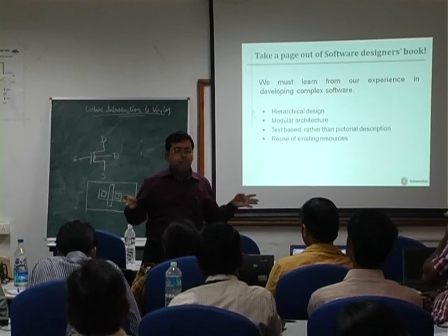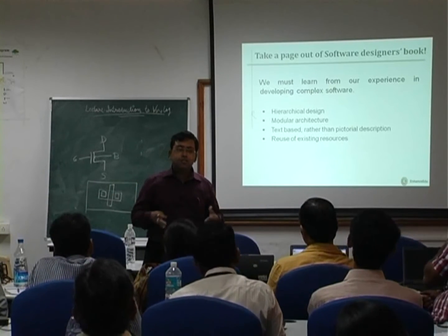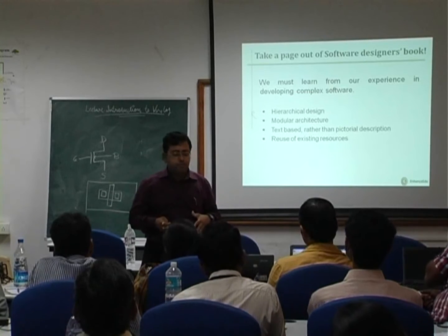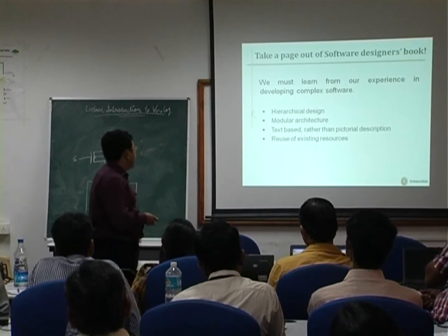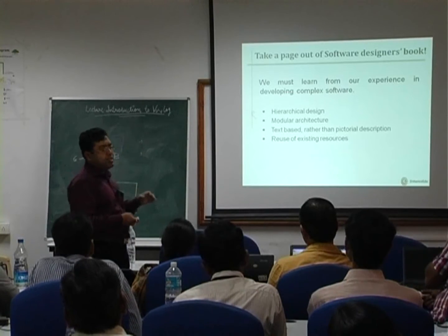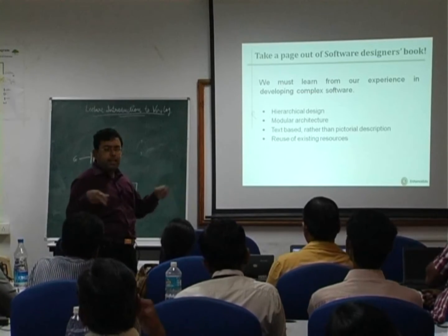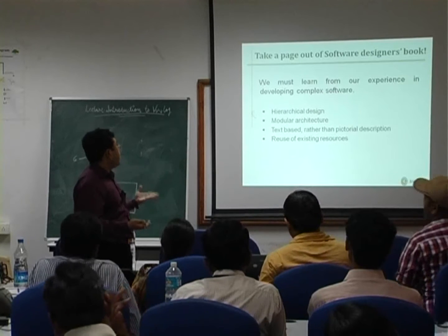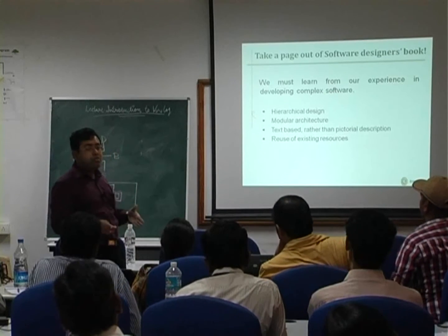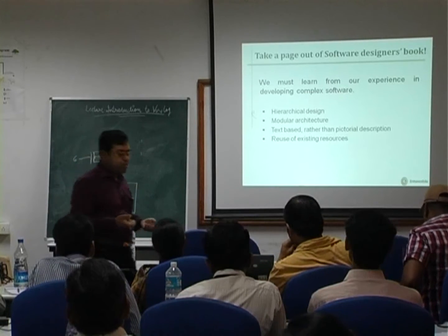And once the elementary level modules are developed, they can be integrated into the whole system. That is what we really mean by hierarchical design, in which we split a system into its subsystems, and the subsystems into sub-subsystems, and so on, ultimately arriving at elementary level modules which you can develop and integrate into a design for the whole.